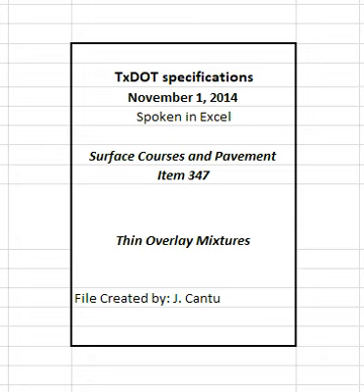For mixtures designed in accordance with Tex-204-F, Part 4, the engineer will use a department SGC, calibrated in accordance with Tex-241-F, to mold samples for laboratory mixture design verification. For molding trial batch and production specimens, the engineer will use the contractor-provided SGC at the field laboratory or provide and use a department SGC at an alternate location. The engineer will make the contractor-provided SGC in the department field laboratory available to the contractor for molding verification samples.